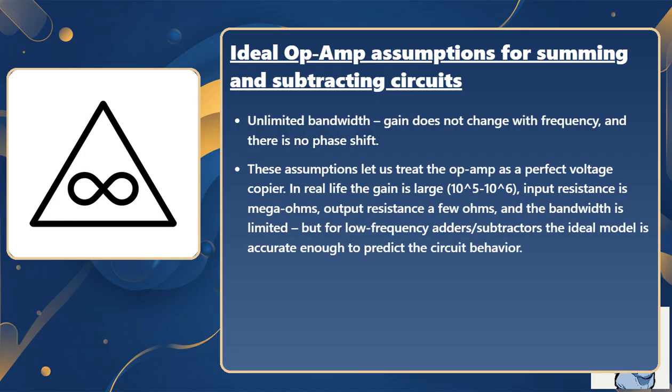In real life, the gain is large, 10 to the 5 to 10 to the 6. Input resistance is megaohms, output resistance a few ohms, and the bandwidth is limited. But for low-frequency adders and subtractors, the ideal model is accurate enough to predict the circuit behavior.